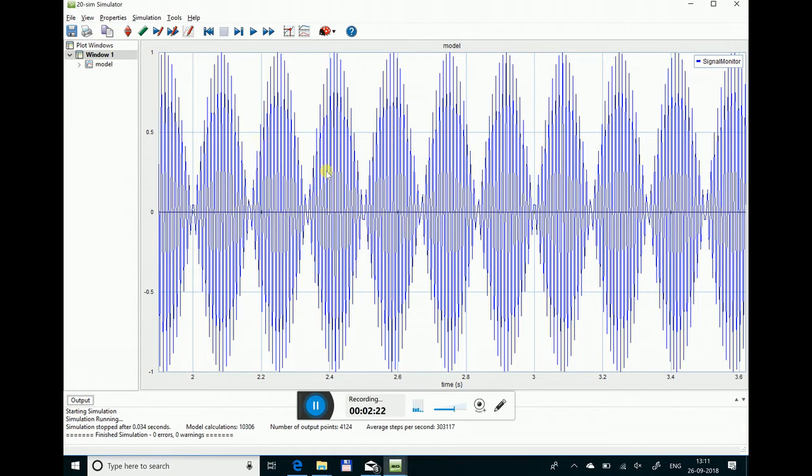The only thing is that I see an output waveform ranging from -1 to +1, whereas my DAC supports from 0 to 5 volts. So I would like to have a change of offset for the signal, which I can do by adding in mathematics to it.